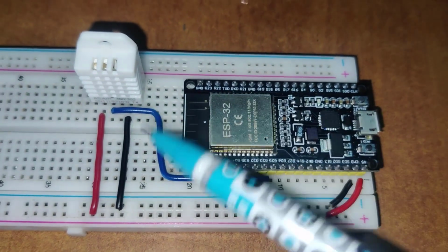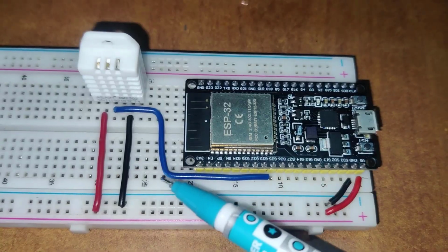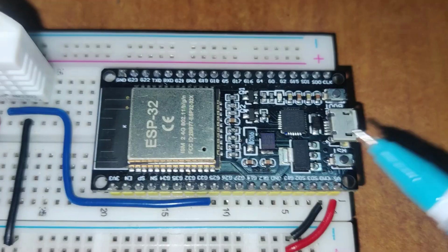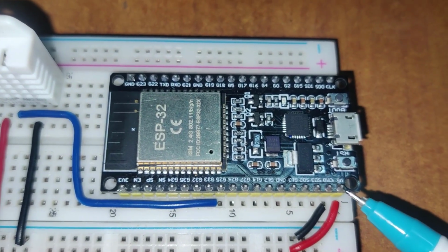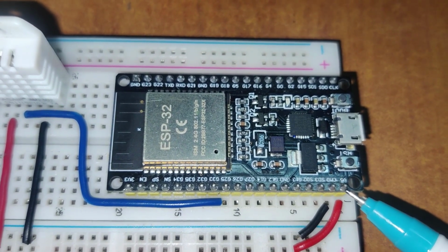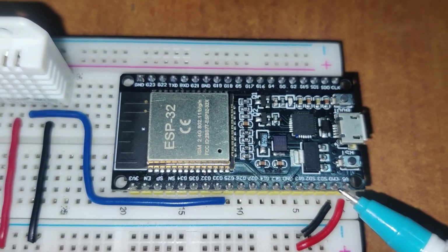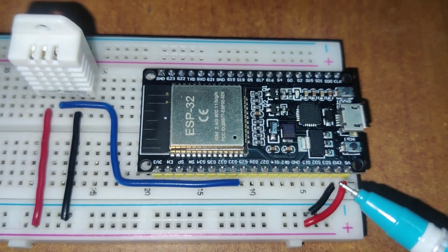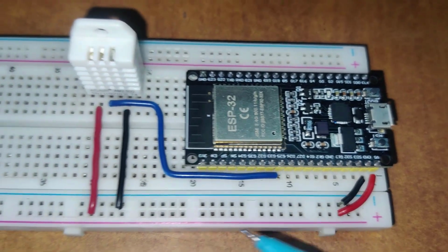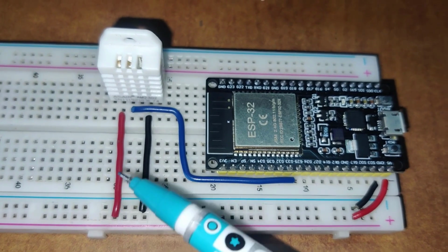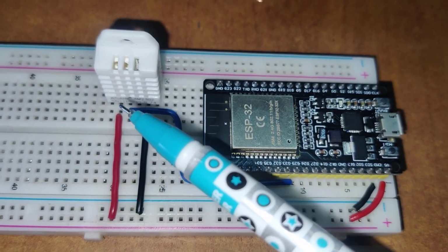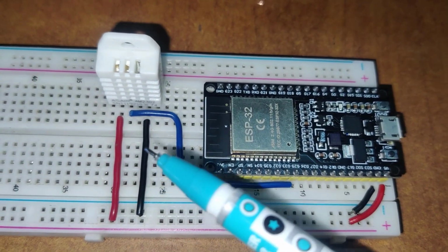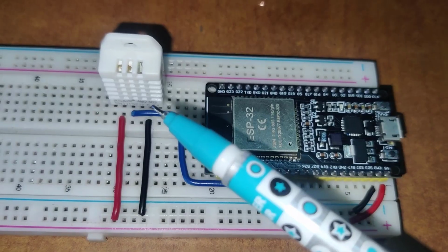So now I have connected this sensor on the breadboard. Clearly you can see here, in the ESP32 the first pin is the 5 volt VCC pin and the second pin is the ground pin. So I have used wires to connect 5 volts to the breadboard as well as ground to the breadboard, and the 5 volt supply is provided to the first pin of the DHT22 sensor, and the fourth pin is the ground, so we have connected the ground to the DHT22 sensor.